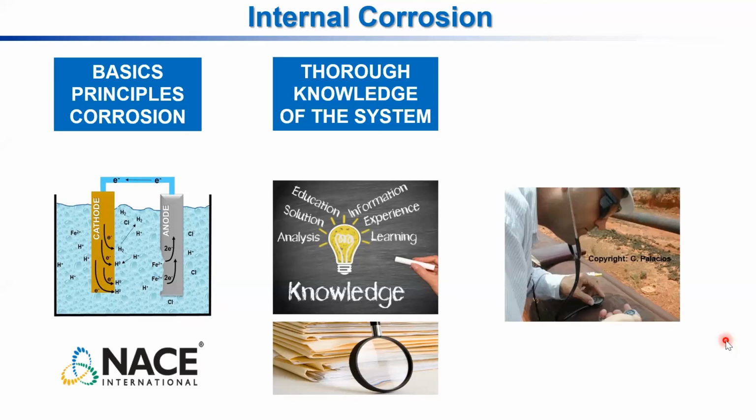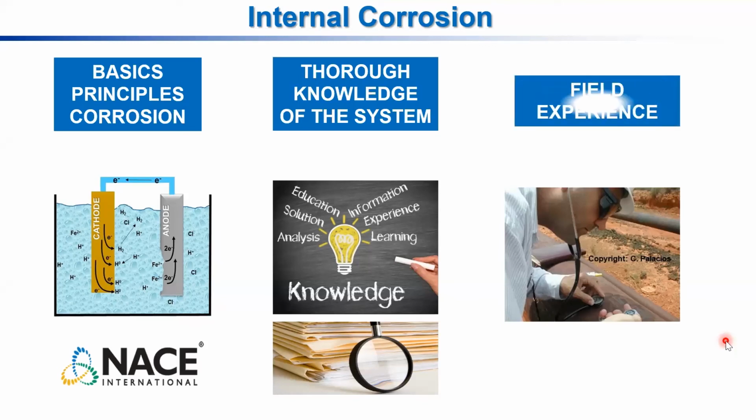Be in the field. You need to have field experience. Here, you may think I'm crazy. That's me basically with a stethoscope listening to the pipeline. What was I listening for? The slugging, the flow, how I was listening to the frequency of slugging. Why? Because with that frequency of slugging, I wanted to verify my flow model to see if the flow model was predicting what I was listening to in that moment.